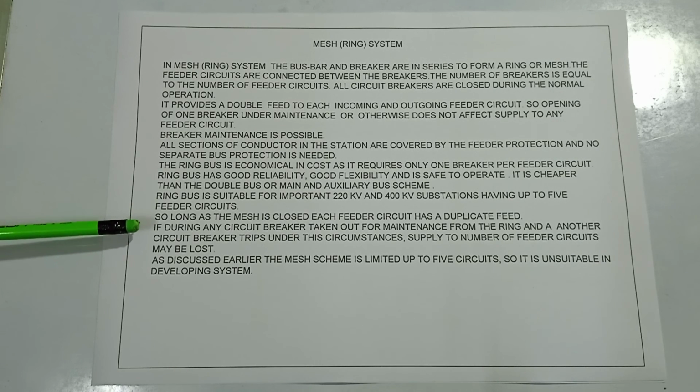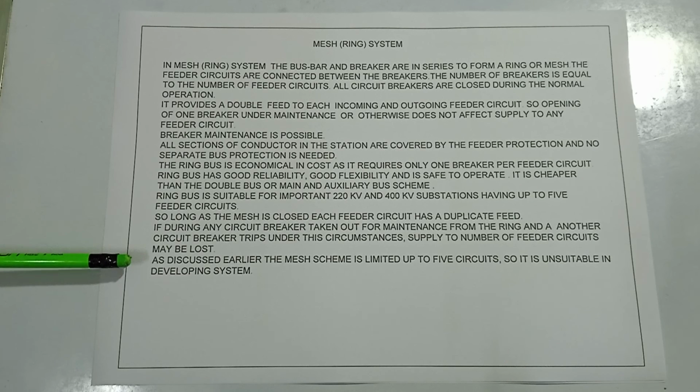If any circuit breaker is taken out for maintenance from the ring and another circuit breaker trips, under these circumstances supply to a number of feeder circuits may be lost. As discussed earlier, the mesh scheme is limited to up to 5 circuits, so it is unsuitable in a developing system.